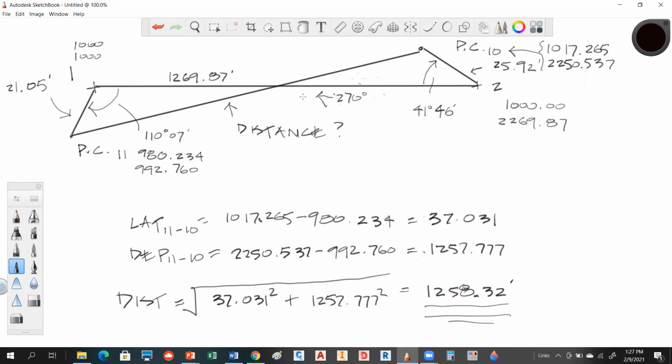Yeah, so we wouldn't just use that to solve it on its own. We would want to be more exact. Yeah, if we needed, but here's the other thing you could do, and we do this all the time out in the field. If I don't really know what a direction is, I just assume something. Later on, I can take my figure and rotate it. Once I figure out that this line is not north, let's say it's actually 81 degrees, 12 minutes, and 32 seconds, the angle between what I called it and what it is, that's my rotation angle. So I could rotate everything by that amount. But in this case, we weren't looking for that, so it didn't really matter. Okay, does that make sense then?